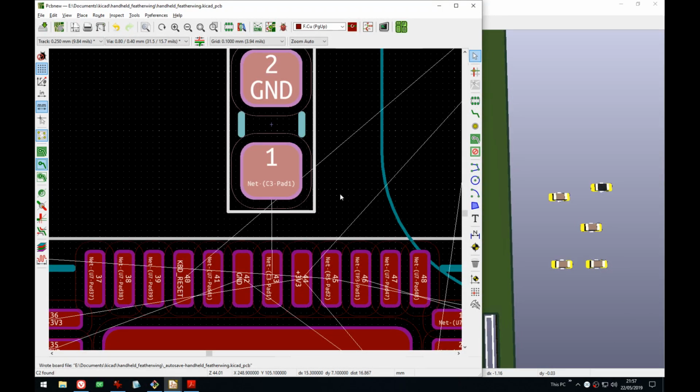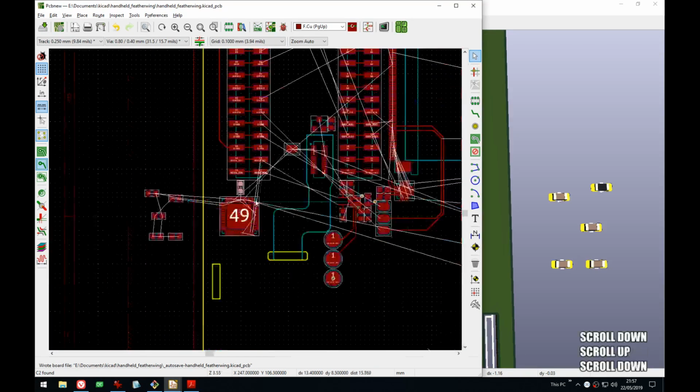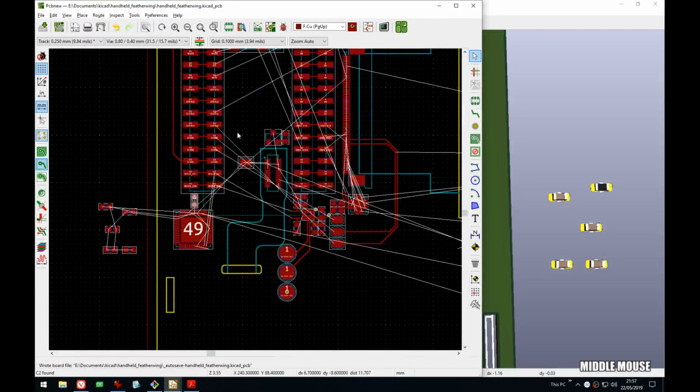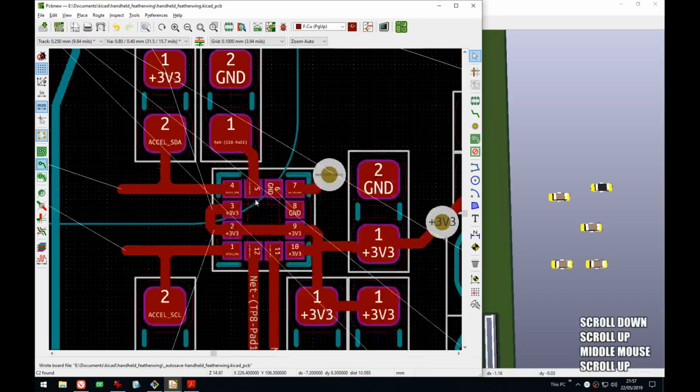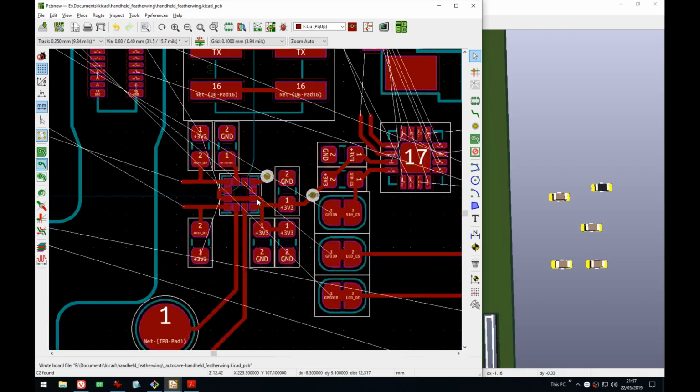You definitely need hot air for QFN. If it has a pad, you could maybe get away if it doesn't have the middle pad, but everything here does. And the LGA, you just need hot air or a reflow oven. There's just no way, because there's no access to the pins.